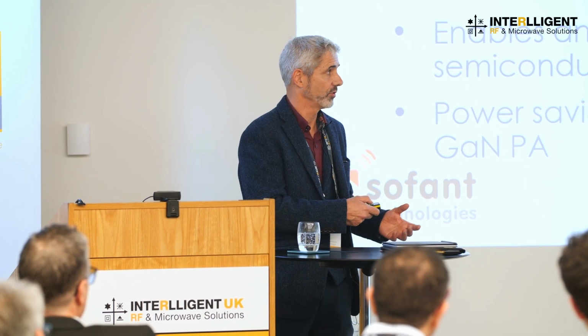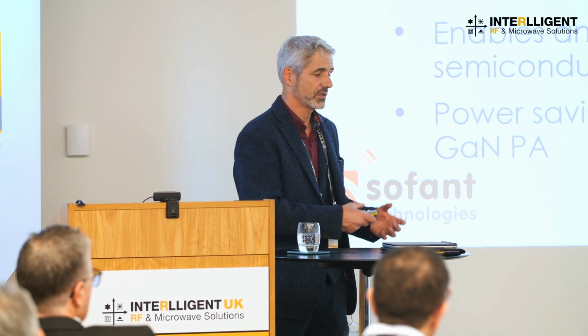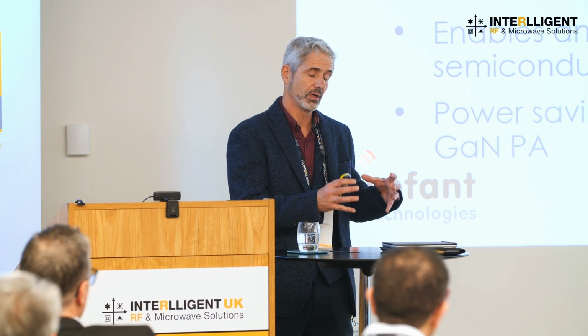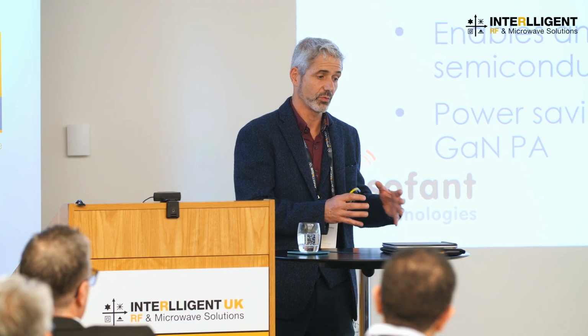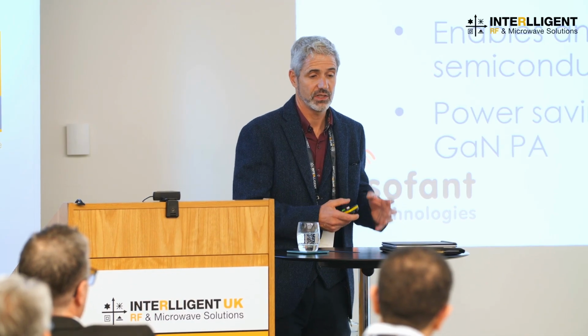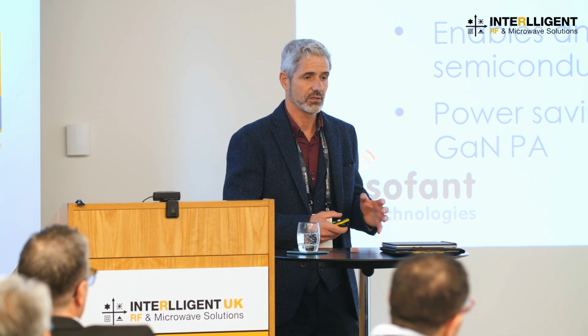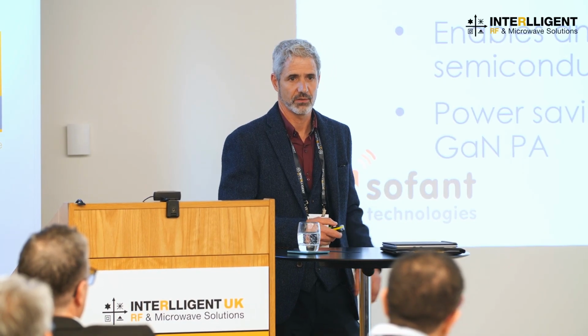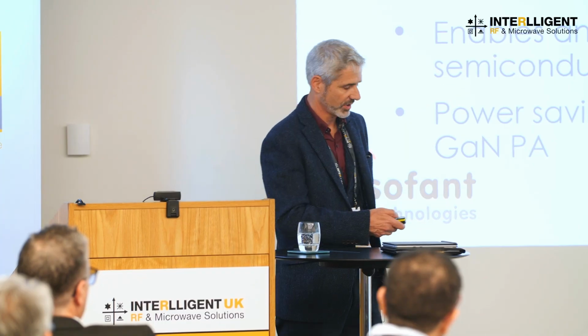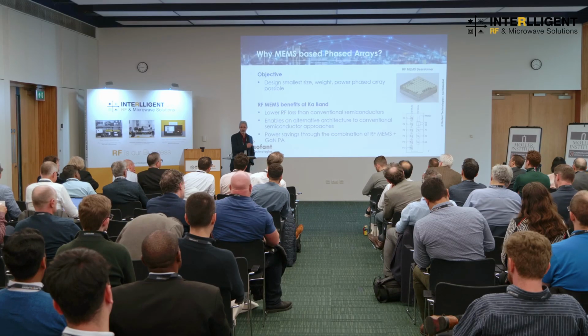The conventional approach has additional functionality, but they generally group more components into a single chip to drive multiple antennas. So we've gone intentionally with less integration. The reason we do that is because that means less loss, and I'll cover that later. So it's a very simple looking chip, but there's a reason why we haven't put more into the chip.